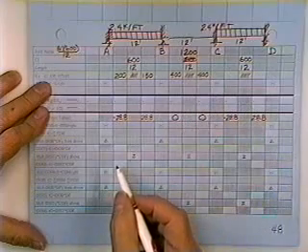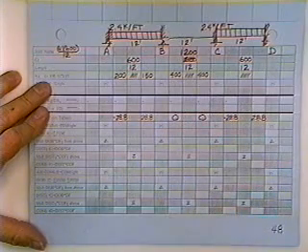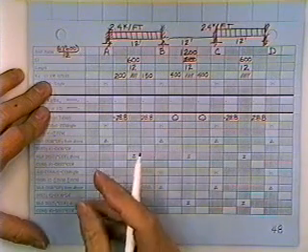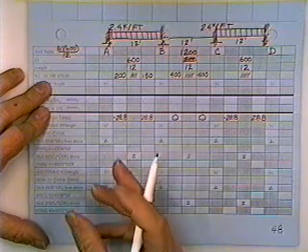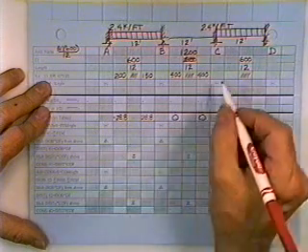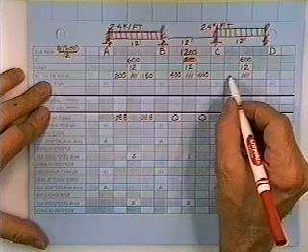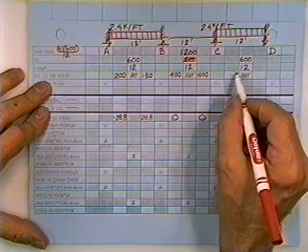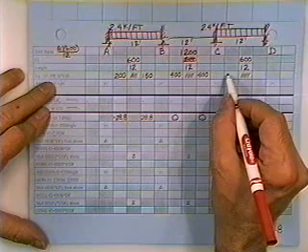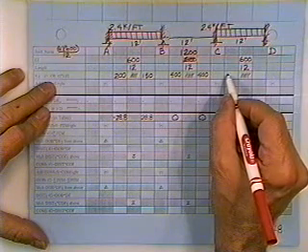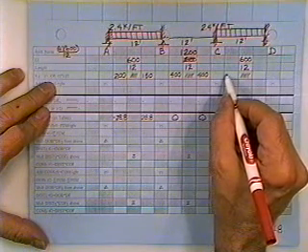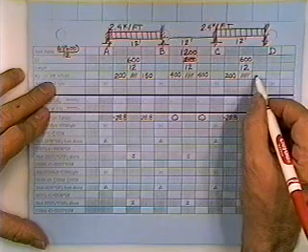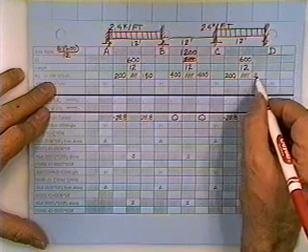These numbers are relatively how stiff the beam is. The beam actually picks up moment in that proportion when you tell the guy to let go of his wrench. As I stand at C and look towards D, I see no pin and quit. I see a wall, and therefore the stiffness is 4EI over L. 4 times 600 over 12 is 200. And as I stand at D and look back at C, I see 4EI over L, that's another 200.